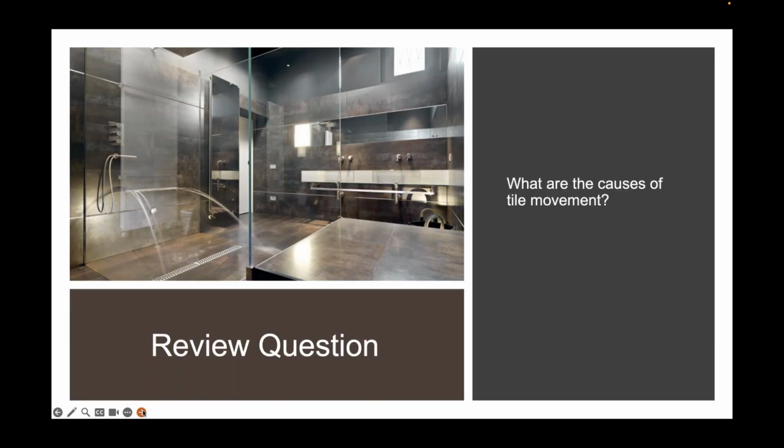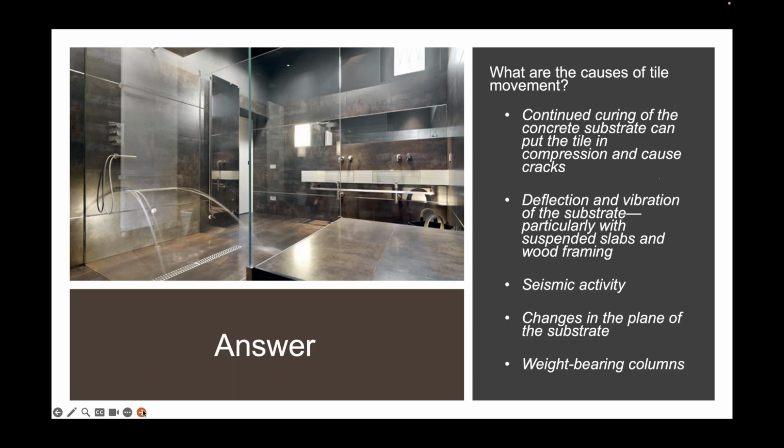All right, review question. What are the causes of tile movement? The continued curing of concrete, deflection and vibration of the substrate, seismic activity, changes in the plane of the substrate, and weight-bearing columns.